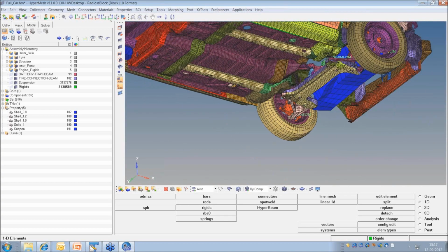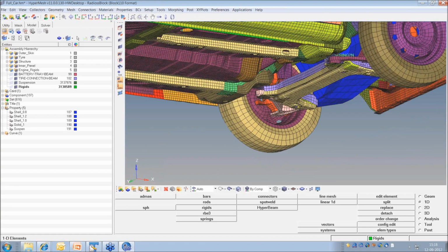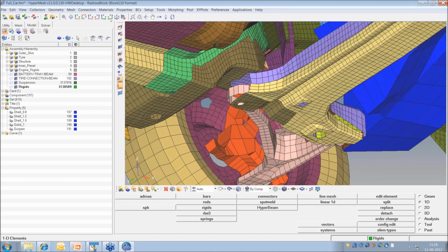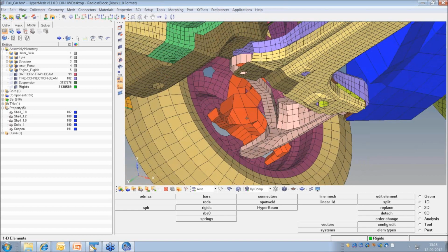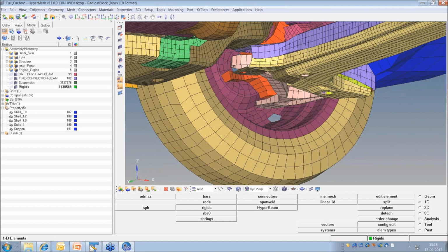It means it should allow the rotation only along z-axis. So at these two places, it should allow the other component to rotate in z-axis. So that is the purpose. So for this joint, we will use type-8 spring. As I mentioned in my PPT slide, for joints we'll be using the type-8 spring, and this type-8 spring has to be of 0 length. So that is one thing to keep in mind.